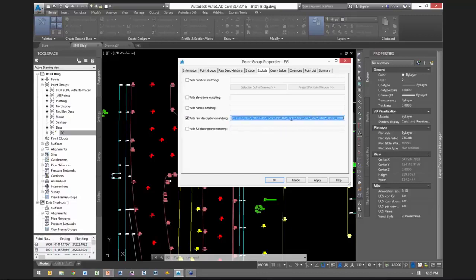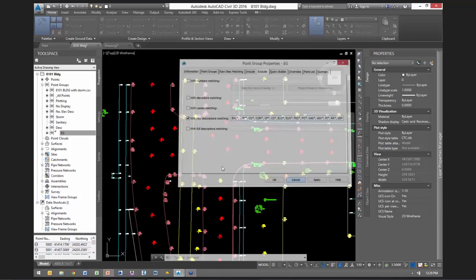So again, people in the field need to be programmed according to how they're doing that. If you have 4 different crews and they have 4 different methods of surveying, it's going to make things a little tricky. Otherwise, we have to have 4 different point groups in there, or we have to have 4 different sets of survey codes. The more you can standardize the way your teams are surveying, the more streamlined and standardized you can make this Civil 3D template.